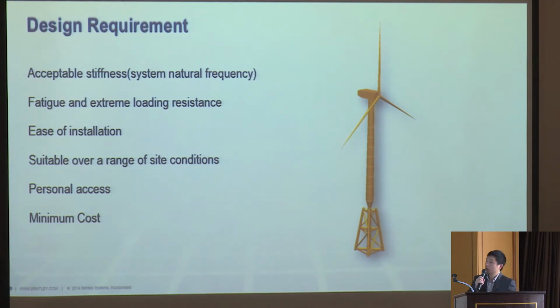For a new turbine foundation structure design, we need to consider all the design requirements listed here. First, the total structure should be designed with an acceptable stiffness. That means we have some requirement on the system natural frequency.